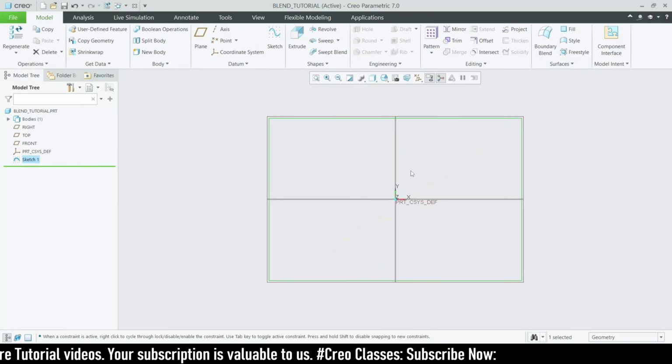Once you go for the extrude, we can create a solid part of this. Same way, if you go for the blend, you can have these two options: sketched sections and selected sections. Let me just close this and go for the blend. Now you have sketched sections and selected sections. Once you have already created a 3D model, or you already have two or three parts, you can directly go for the selected sections and select your items so that they can be blended.